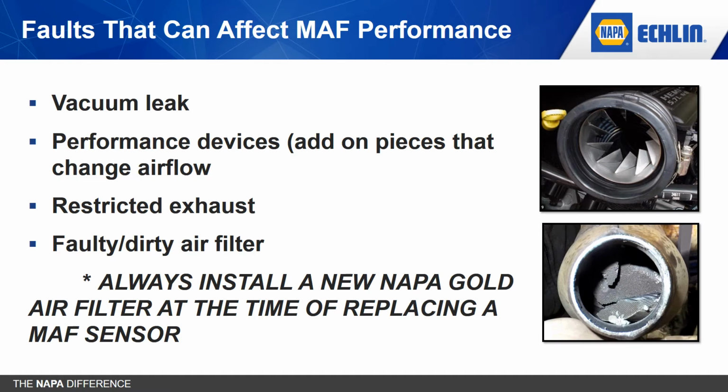Or, if an oiled-style, reusable filter is used, keep in mind it may release oil, which will coat and contaminate the sensing element as well, and this too may cause the mass airflow sensor to give erroneous data.